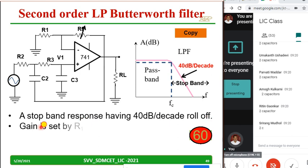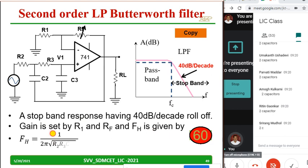Gain is set by R1 and RF, and FH is given by 1 by 2 pi square root of R2 R3 C2 C3. Just take a minute and copy down, but this I have highlighted. It's not 20 dB, it's 40 dB. Many students in the exam forget to say 40 dB. They write 20 dB.